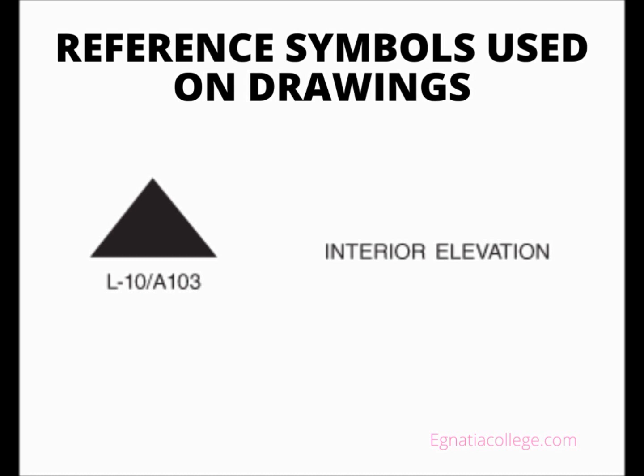The detail drawing symbol also can be found on the first floor plan, located just above the section view symbol at the left end of the building. The direction of the rectangular flag indicates that it is also drawn as though viewed while facing north. That detail, which is at a larger scale, 3/4 inches equal 1 foot, than the building sections, 1/8 inches equal 1 foot, is number A4 on sheet A502. Detail A4 includes further detail symbols, such as one about halfway up the wall referring to E2 on A504, an expansion joint detail, at 3 inches equal 1 foot.